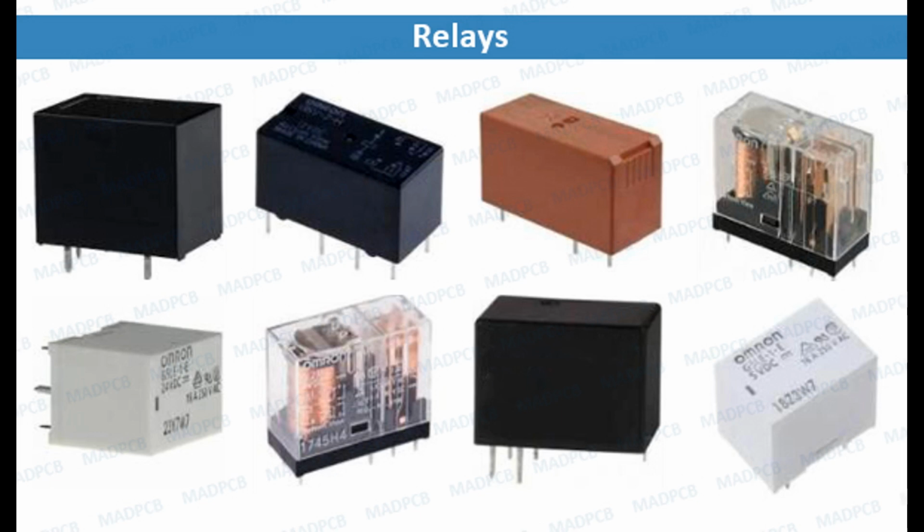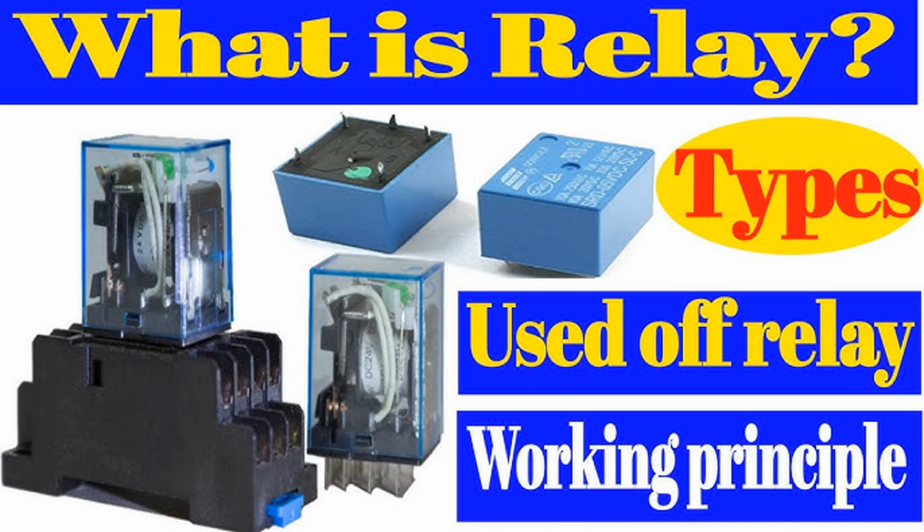Working principle. Activation: when the control signal is applied to the coil, the relay is energized, but the contacts do not immediately change state due to the delay mechanism. Timing delay: the timing circuit begins counting down the preset delay period. The method of timing can vary depending on the relay design, mechanical, electronic, etc. Contact action: once the preset delay time expires, the relay contacts will either open or close, depending on their configuration. Resetting: after the delay action occurs, the relay will remain in its new state until the input signal is removed or the relay is manually reset, depending on the design.